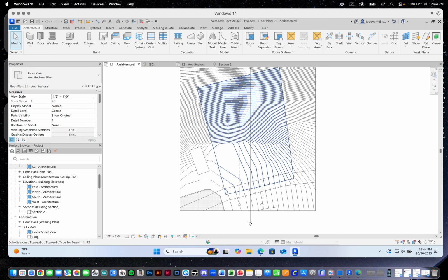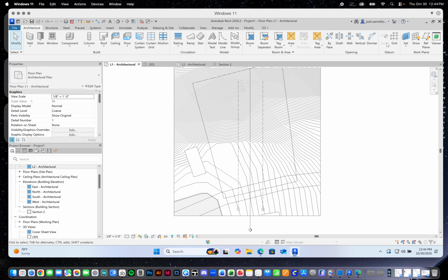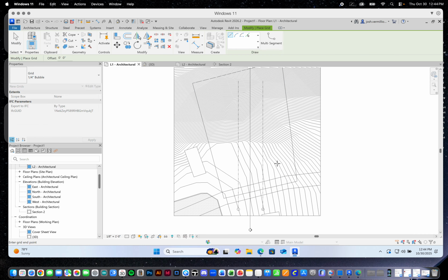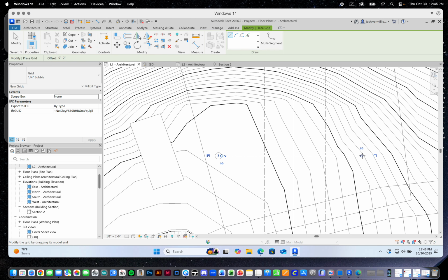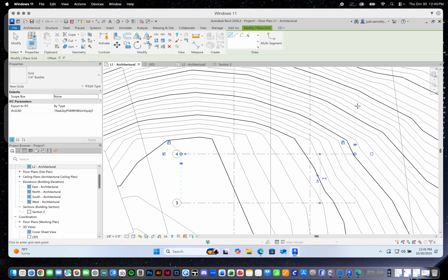All right, and now I'm going to make some east-west column grid lines. So I'm going to start over here and move this way. There we are. Then I'll do it again, 24 feet up. So these bays are going to be 24 feet each, so we'll have structural bays of 36 by 24. I'm going to have 3 bays, so I have to draw 4 of these.